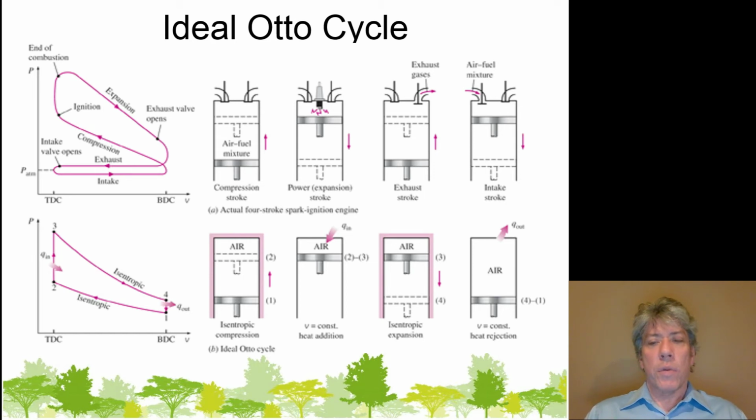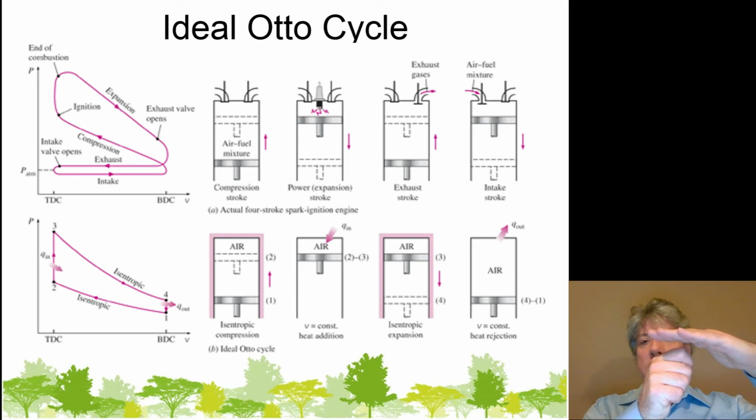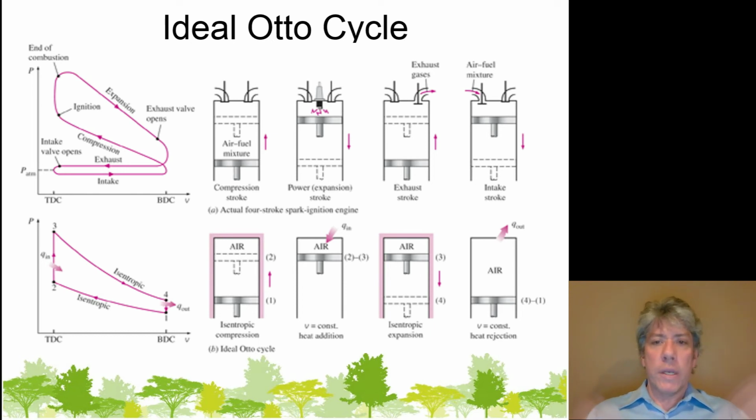So notice that we're really capturing the whole point. And if you think about it, it makes sense, right? Because after the exhaust valve opens and the piston in the real device goes up pushing the exhaust gases out, where does it end up? It ends up back at bottom dead center by pulling in more air and fuel. So we could just let the piston sit there in our idealized cycle, since not much work is associated with moving that piston up and down, and just imagine the air cooling down and its thermal energy being lost to wherever.